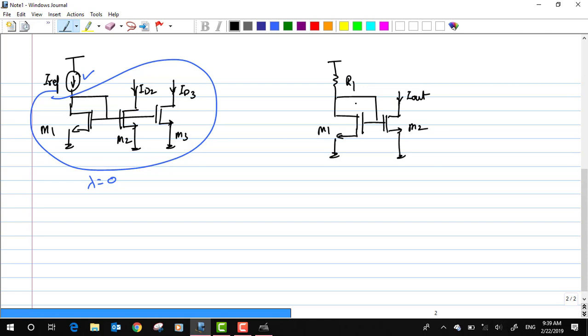Okay, so the most generic way to realize this I reference is by making use of a resistor, and when we try to do so, then this would obviously create a current which is I reference. Just because there is a potential difference between this VDD and this particular point. Whenever there is a potential difference across my resistor, obviously the current would start flowing, and I am just assuming that I have selected the resistor R1 suitably such that the required I reference is being generated through this device. And our task in this entire discussion is that this I reference should not depend on my V supply or any variation on my V supply. So that is what we will try to understand through this.